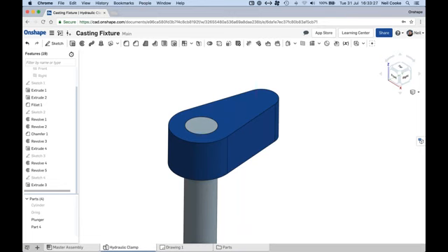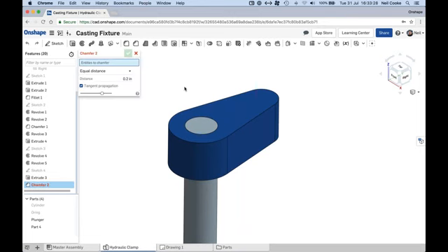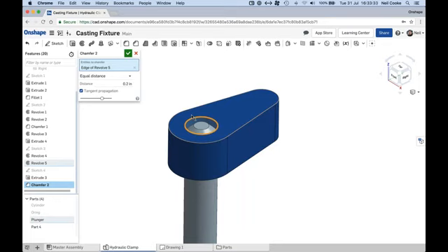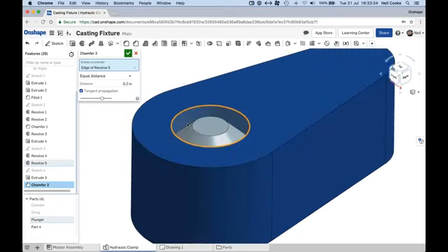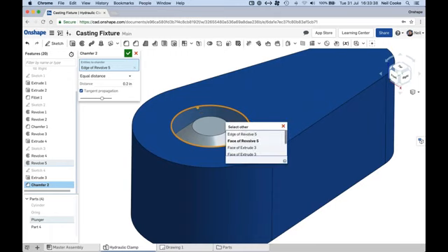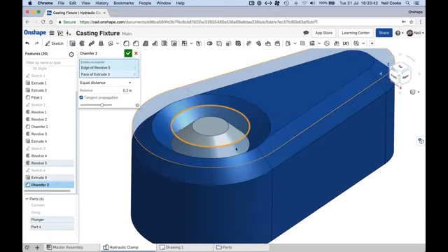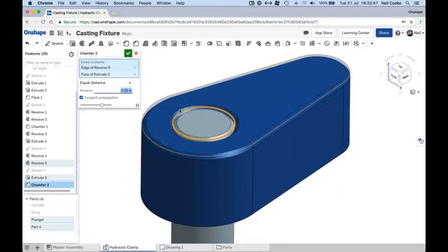You can also do things like create chamfers over multiple edges. So, for example, there I've selected the top of the plunger, and also you can pick the edge of the extrude and build a chamfer on two different parts at the same time, if you wanted to do that. So the fact that it's multi-part as opposed to multi-body in SolidWorks, you can do things like add chamfers across multiple parts, and it's a lot easier to control.